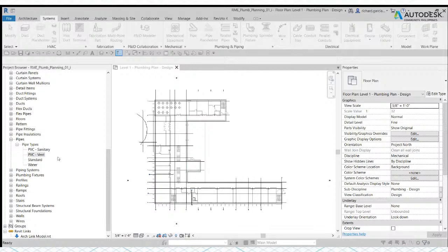Okay, so let's say, for example, for my pipe settings here, so these are some of the settings. Again, if you have time, go to your pipe settings, press F1. So you will now see all the meaning of this. So in my case, let's say, for example, I want to change the pipe connector tolerance. So I don't want a 5-degree tolerance.